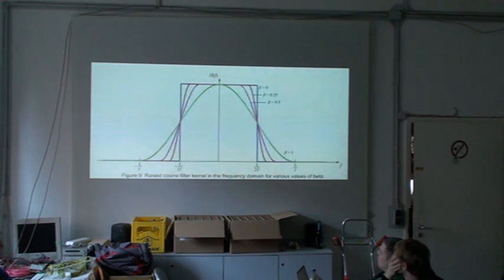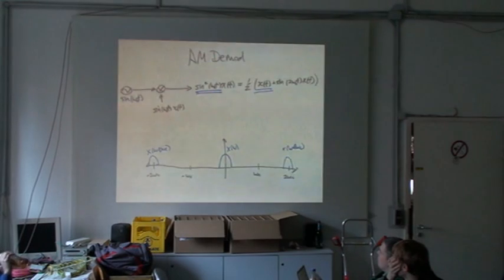Now, intersymbol interference is not the end of the world. There are ways to deal with it, but it complicates the design of your receiver. So for any application, it's a given trade-off between excess bandwidth, transition bandwidth, and receiver complexity, and you'll pick the appropriate parameter for your application.